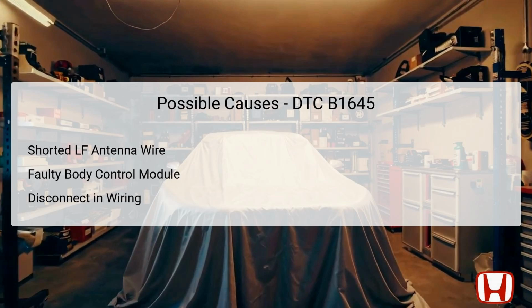Lastly, accidental disconnections or cuts in the wiring harness, particularly near the driver's door, can lead to this DTC being stored.